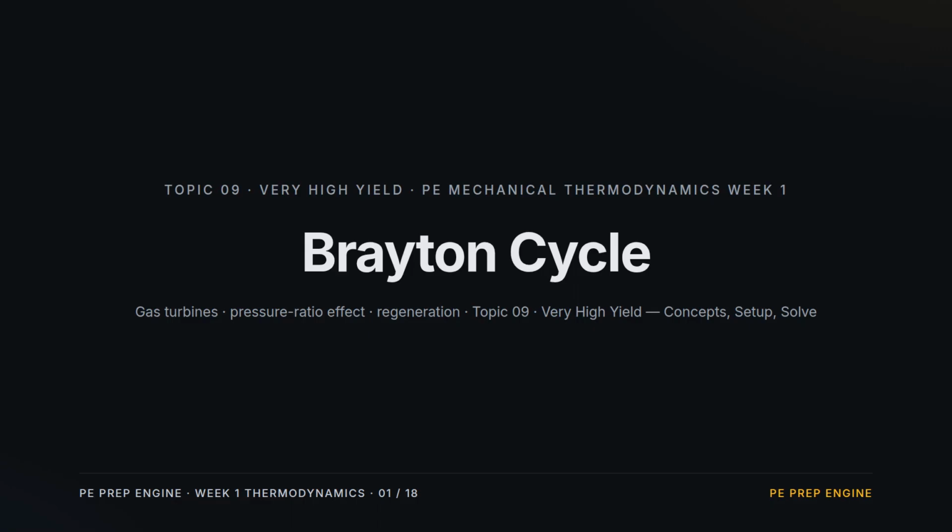Topic 09. The Brayton cycle. Gas turbines. Very high yield. Expect 2 or 3 questions. Brayton is Rankine's gas phase cousin. Same 4-device closure, but air instead of water. Pressure ratio instead of saturation tables. Ideal gas relations instead of steam table interpolation. If you mastered Rankine, this comes fast.